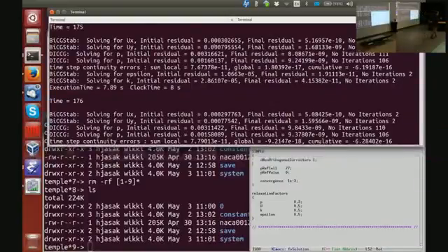When you formulate linear equation sets for each of your equations and call the linear equation solver, it will solve those equations. But that doesn't indicate overall convergence, because your equations are coupled to each other and they're also nonlinear.